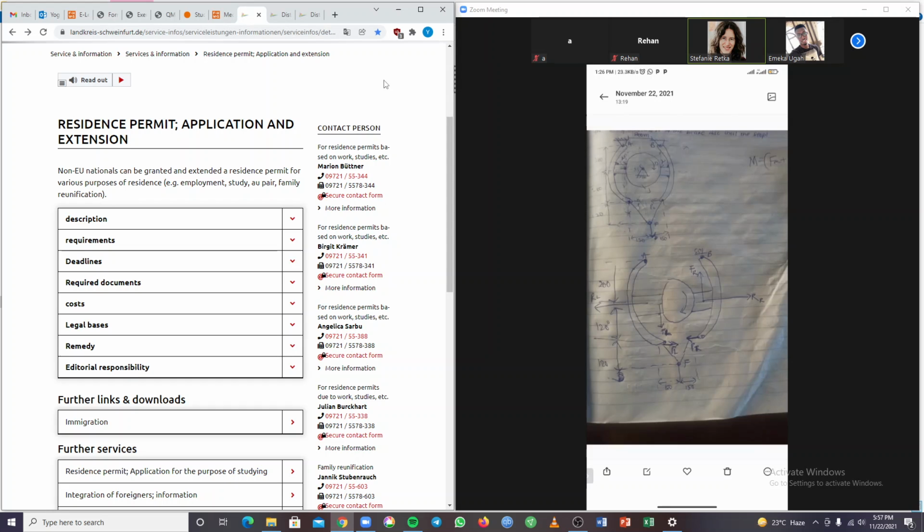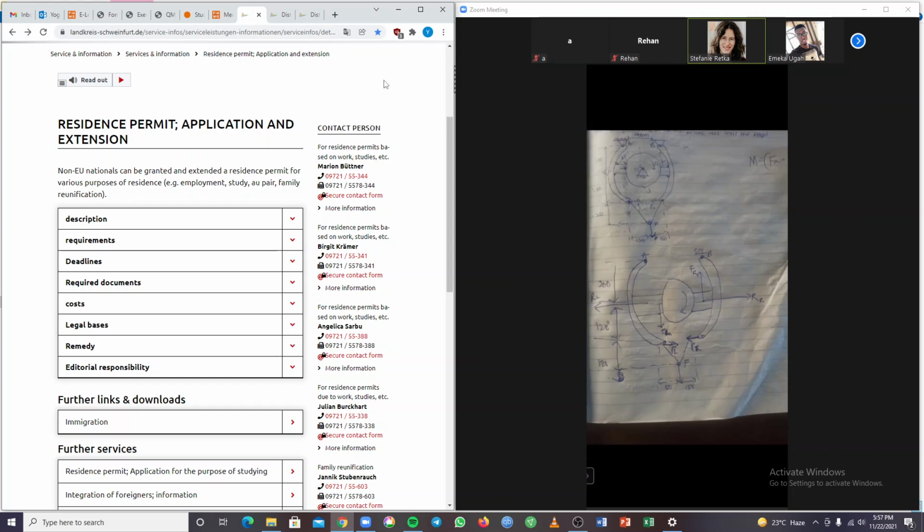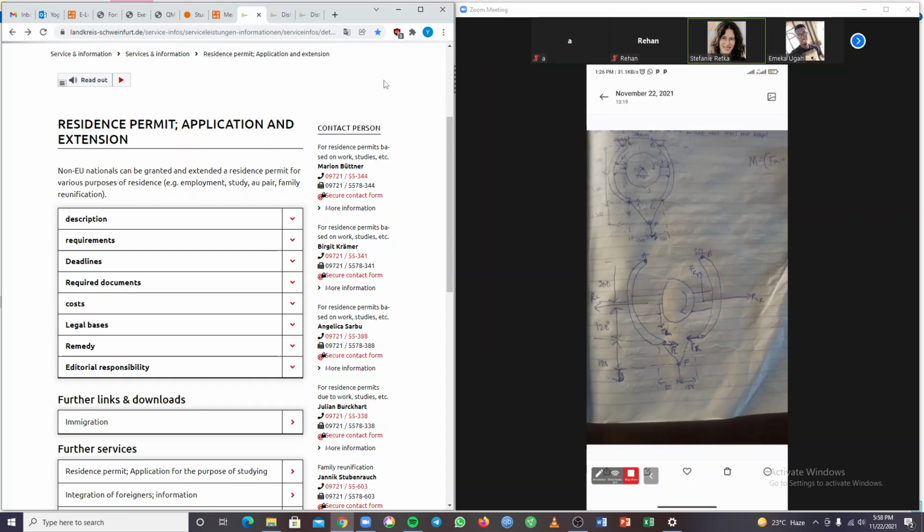In statics, there's an arbitrary system, whatever it is, and you free the system from the surroundings. You draw your line around the system, cutting through the hinge supports in A and in B. Then you draw this system and substitute the supports by the support reactions, two support reactions for each hinged support. No other forces at all. Just draw the figure given in problem 316 and substitute the supports by the support reactions.